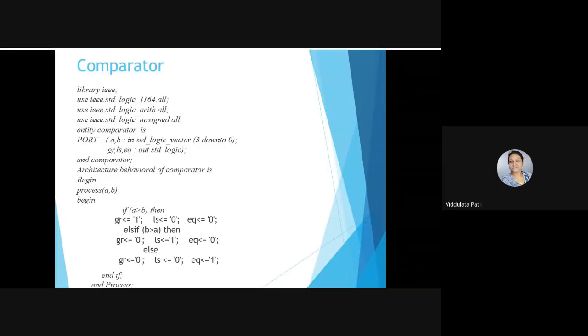So what is meant by a test bench? As I said earlier, it is the code which will test whatever VHDL code we have written. For that we need to give certain inputs, and depending on those inputs it will give us certain outputs, and from that we can verify whether the code that we have written is correct or not. So we are simulating that code and deciding whether it is correct.